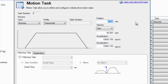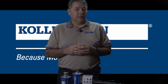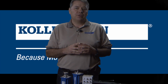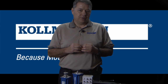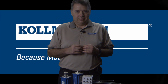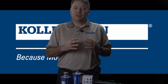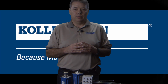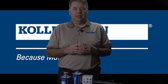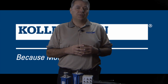position units. In the unit screen, you will notice that there is disc angular and disc linear. Disc angular is concerned with positioning the load in angular units, such as degrees, and working in 1 revolution of the load. Disc linear is concerned with positioning the load in linear units found on the circumference of the load as based on the radius. Keep in mind the radius with which you might be working may lie physically inside the load.